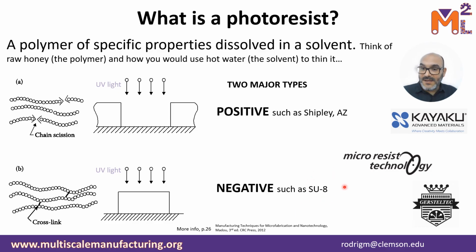And it's particularly SU8, because as a community, we have been using SU8 for a number of years, and there are many works that are based on SU8. Other photoresists as well, like AZ and other positive photoresists, they also carbonize, right? So make sure that you check what objectives you have in your project, what kind of dimensions you're looking for, what kind of thicknesses you are looking for, because maybe in some cases the positive photoresist might make more sense than the negative photoresist. So always check.